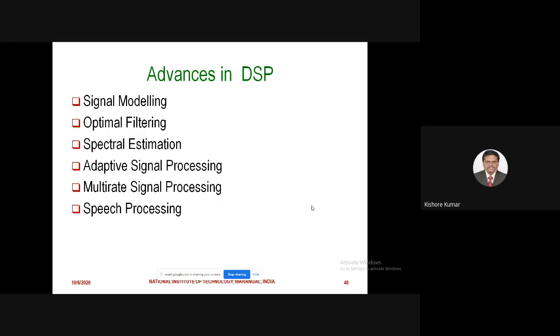That's why in the case of filtering, we convert the S domain into the Z domain by using the Z transforms. You know that in the case of analog filtering. When you want to design a digital filter, normally we will have a problem in the S domain. You heard about that? We will have a problem in 1 by S plus 2 or 1 by S square plus 2S plus 1. So S is converted into the Z domain. So the S domain is converted into the digital domain.